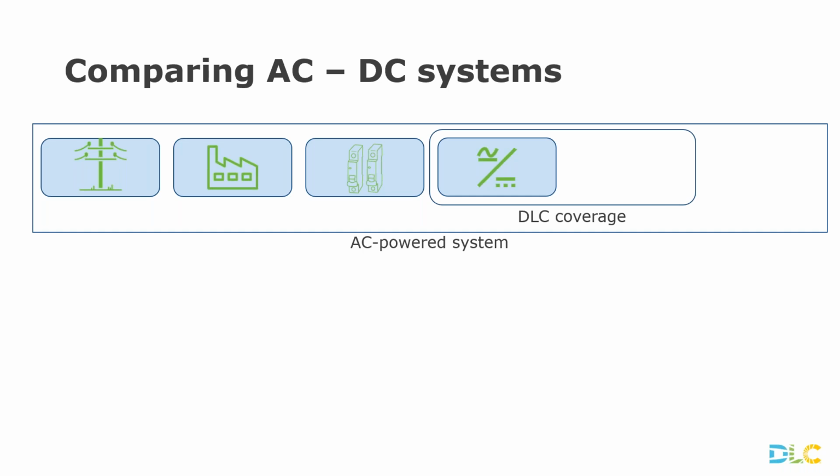So there is the rectification from AC, which is that squiggly line, down into DC, generally internally within the fixture. And then there's optical losses. That little shape is supposed to be a lens. But if you have optics, light bouncing around within the fixture before it exits, all of that is wrapped up in the fixture product performance testing that DLC requires and mandates for AC powered fixtures today.